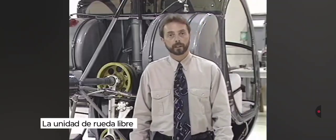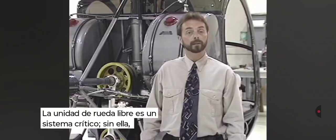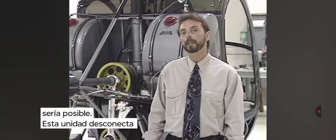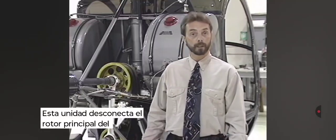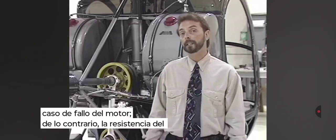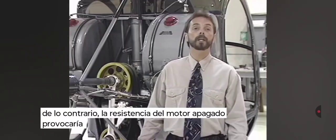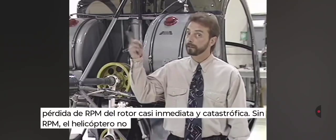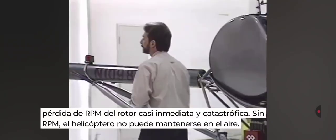The freewheeling unit is a critical system. Without it, autorotation wouldn't be possible. The freewheeling unit disconnects the main rotor system from the engine in the event of an engine failure. Otherwise, the drag of the dead engine would cause an almost immediate and catastrophic loss of rotor RPM. No rotor RPM, no staying up in the air.